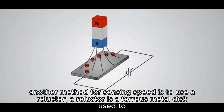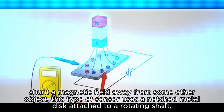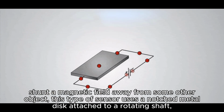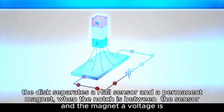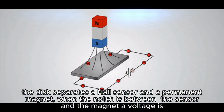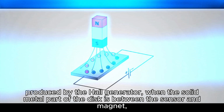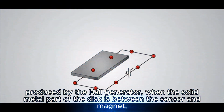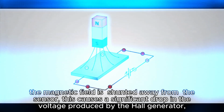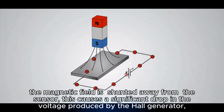Another method for sensing speed is to use a reluctor. A reluctor is a ferrous metal disc used to shunt a magnetic field away from some other object. This type of sensor uses a notched metal disc attached to a rotating shaft. The disc separates a Hall sensor and a permanent magnet. When the notch is between the sensor and the magnet, voltage is produced by the Hall generator. When the solid metal part of the disc is between the sensor and magnet, the magnetic field is shunted away from the sensor. This causes a significant drop in the voltage produced by the Hall generator.